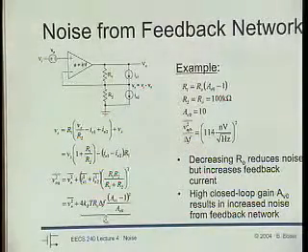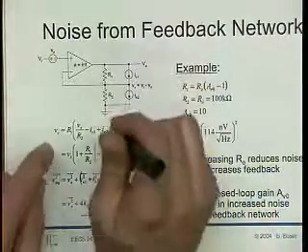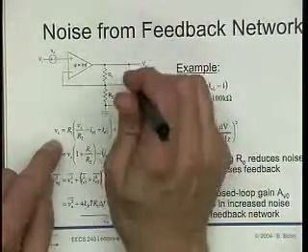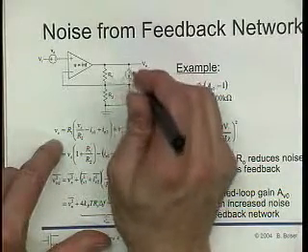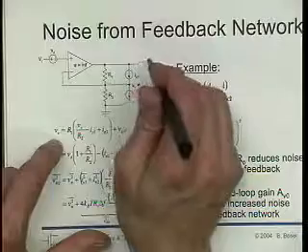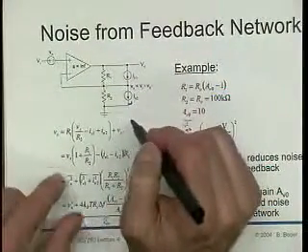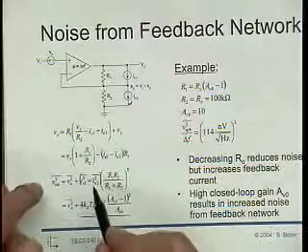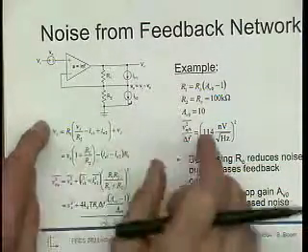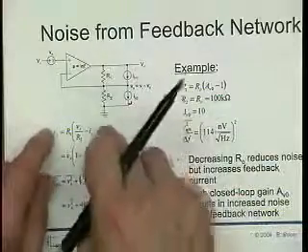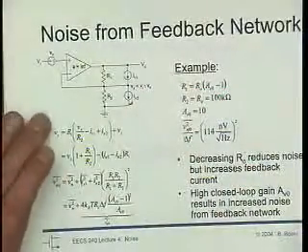Very tedious and very long, and I wrote only about half of the equations here. But basically, I'm calculating the gain from every noise source, and also the input, incidentally, to the output, right? And then I also calculate the gain from the input to the output, and I divide my noise gains by that, and therefore calculate the input-referred noise.